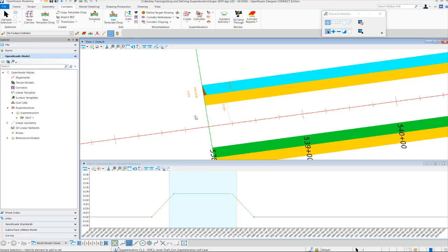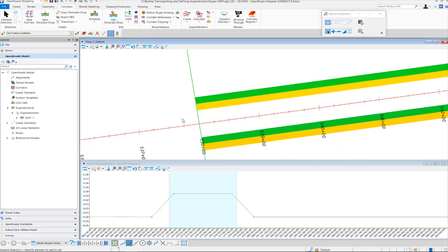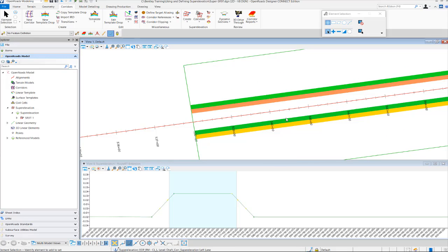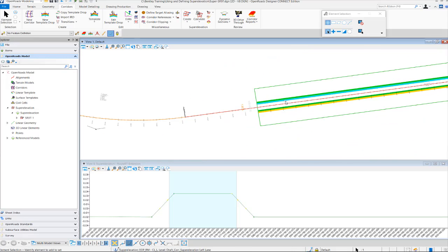Once again, you'll see the dynamic text. I'm just going to click on the slope here and change that from 2% to minus 1.6. That's going to update the text and the transition assigned to that lane. Then I'm also going to select the right lane here for my westbound side, and we're going to change that one to 1.6 as well. So now we have a transition happening here, going from 1.6% to whatever our next cross slope is, somewhere up near the curve.